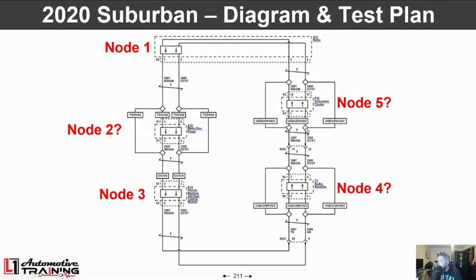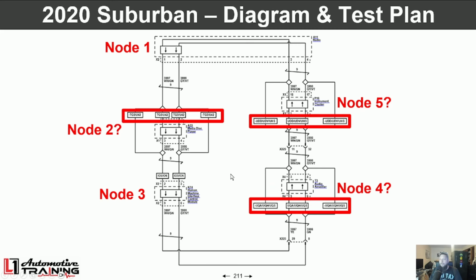Well, it probably has an instrument cluster, but whether it's on the MOST bus network depends upon the type of infotainment system it has. So there are three distinctive sets of RPOs for this vehicle that it could be. So we need to investigate which RPOs this vehicle has, because it may not actually have a CD player.